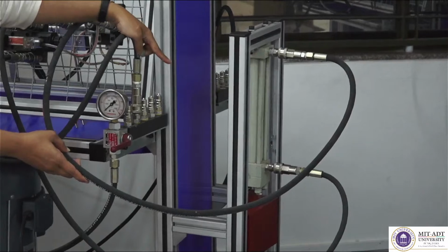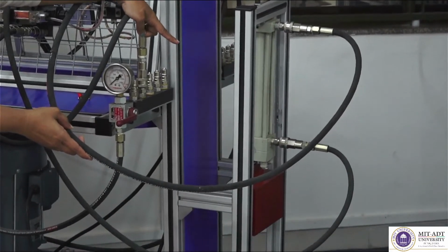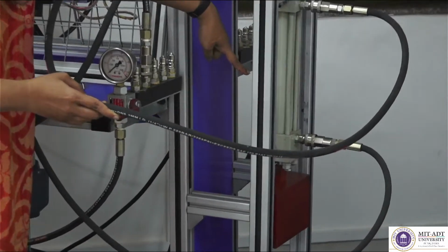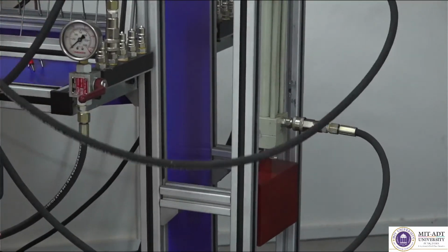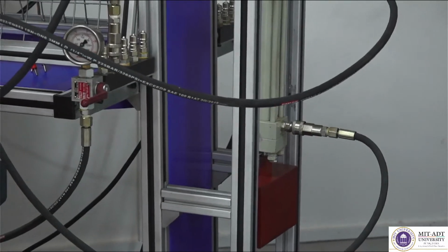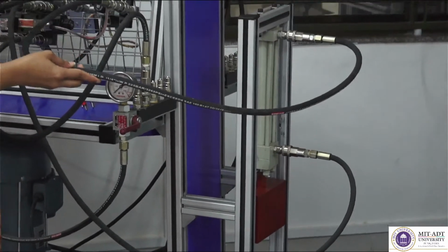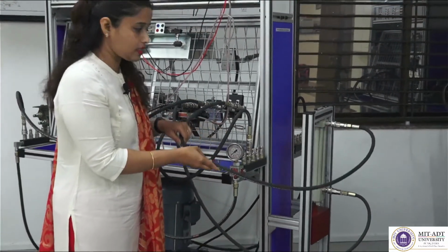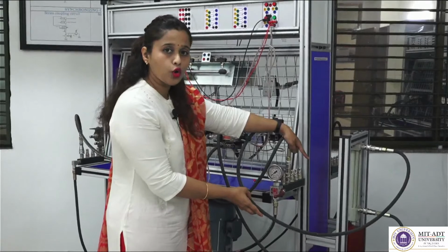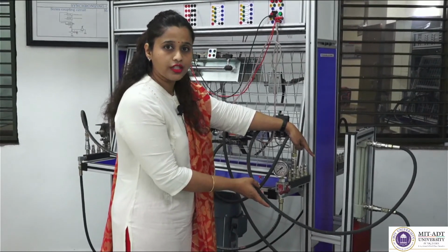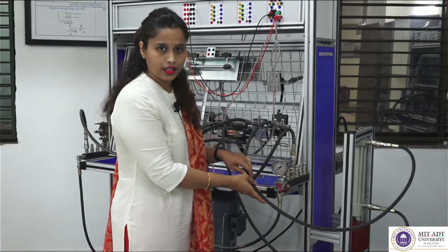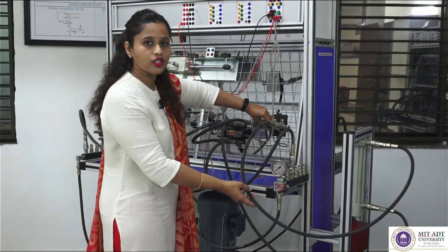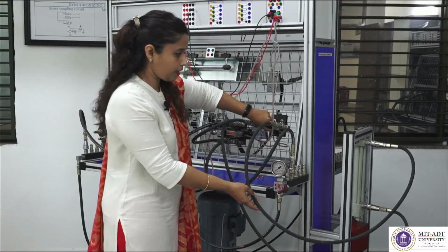But the dead weight of 10 kgs which has been attached over there, so the fluid which is present on downward side of the piston would be capable of holding the weight of 10 kgs as well as creating a back pressure on the piston, so that we can see there would be very slow motion of that 10 kg dead weight in vertically downward direction. Whereas, we can control that motion with the help of this knob which is there on FCV, right.